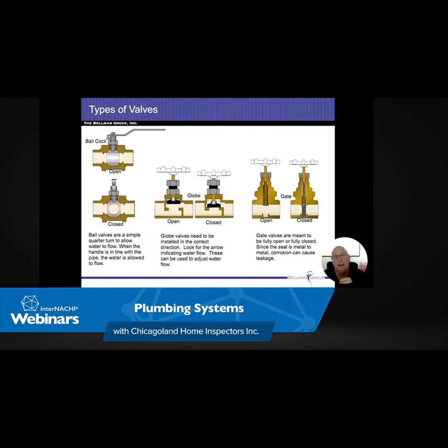This one ends up, when it calls to operate, it allows water to flow and shoots it up there, creating a Venturi effect. That Venturi effect is going to siphon in the water around it, and that's going to get it out of the system. So it doesn't require a battery or charging or anything else with it. It just needs water pressure to be connected to it.